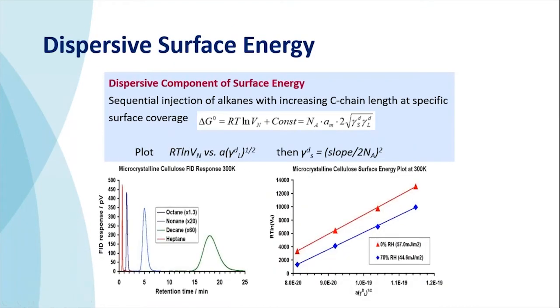So moving on to the interesting bit of the talk, hopefully, is actually looking at surface energy on some biomaterials and how we might apply that to a range of different materials. Before I get to that point, just as a reminder for those not familiar on measuring surface energy by inverse gas chromatography, we typically use a series of straight chain alkanes, nonane, octane, heptane, decane,